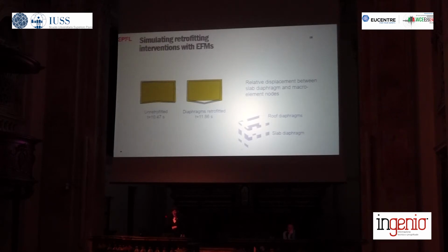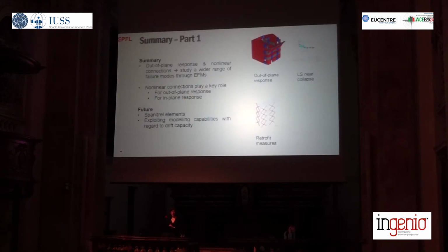If we have the diaphragms retrofitted, but the connections are not retrofitted, then of course we get really that relative displacement between the macro element nodes and the diaphragm nodes. Of course, if we also retrofit the connections that we model just as equal degree of freedom constraints, then the nodes are always in the same place as the diaphragm. Okay, so this is really the first part of the post-diction.